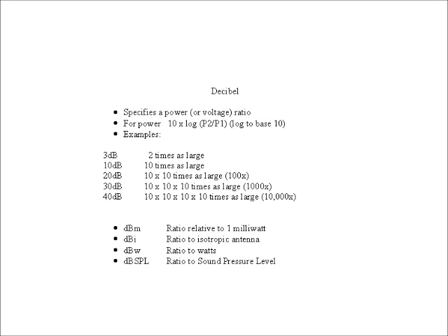And here's some other kinds of dB readings. There's dBm. dB are always ratios. It's a relationship of one to another. So in the case of dBm, it's the ratio relative to 1,000th of a watt. And that's used often in measuring receiver performance.